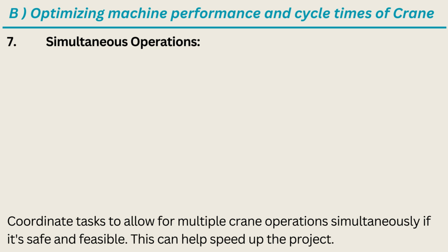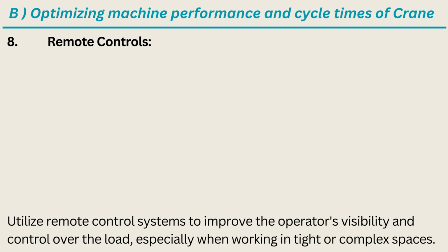Coordinate tasks to allow for multiple crane operations simultaneously if it's safe and feasible. This can help speed up the project. 8. Remote controls. Utilize remote control systems to improve the operator's visibility and control over the load, especially when working in tight or complex spaces.